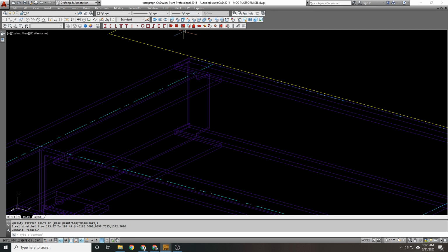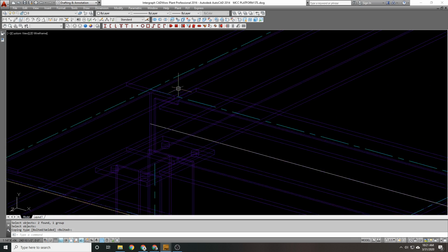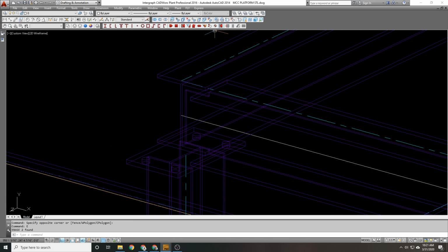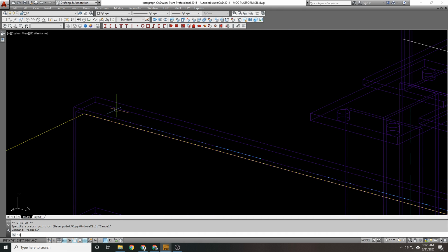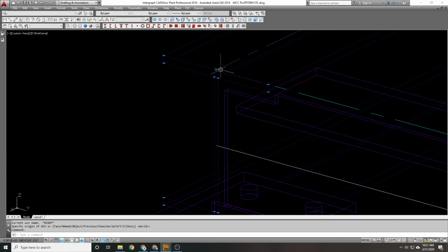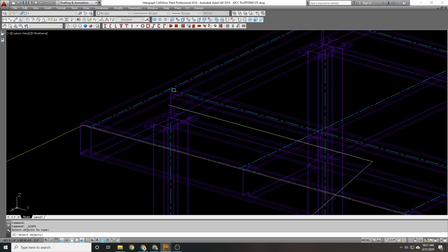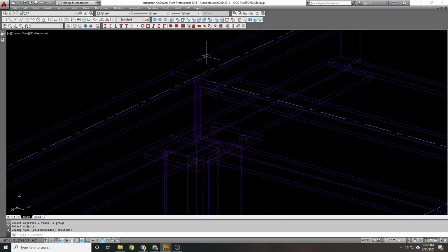So we're gonna cope, bolted, cope, bolted. And this coping plane is still active. I hate it when that happens. And it does happen, where your coping planes will be active still, like old coping planes, and you'll have beams that get split. Turn this back on. Okay. Hopefully that takes. Nope. This side got.